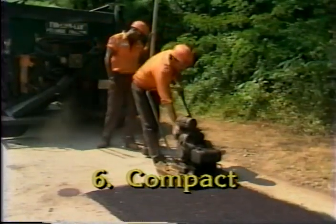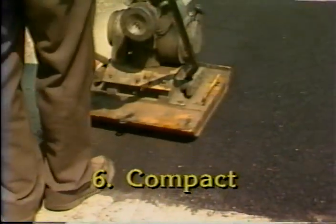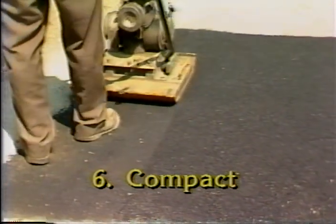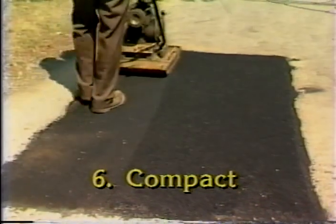6. Compact the material as soon as the asphalt is placed. Compact each lift separately. Compaction of the top layer of asphalt should leave the patch elevation even with the surrounding pavement.